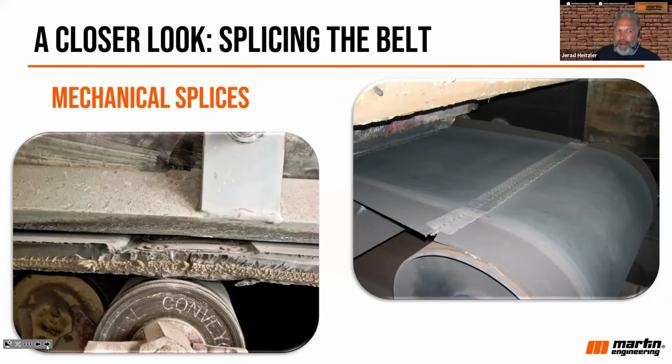And I chose that particular picture on the left to show how a skived belt may or may not work appropriately with skirting systems to seal in dust. So you want to make sure that if you're skiving that belt, you keep that consistent level with the belt as much as you can. In the picture that you see here, dust could escape, and that could cause some problems.